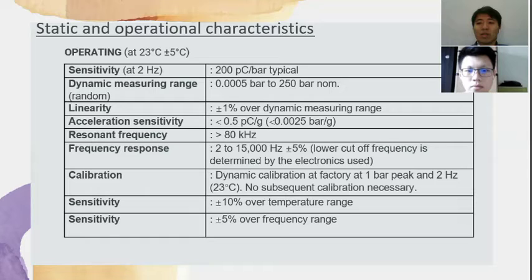Resonant frequency is larger than 80 kHz and the frequency response is from 2 to 15,000 Hz plus minus 5%. No subsequent calibration is necessary for this sensor, and the sensitivity over the temperature range is plus minus 10%, while over the frequency range it is plus minus 5%.